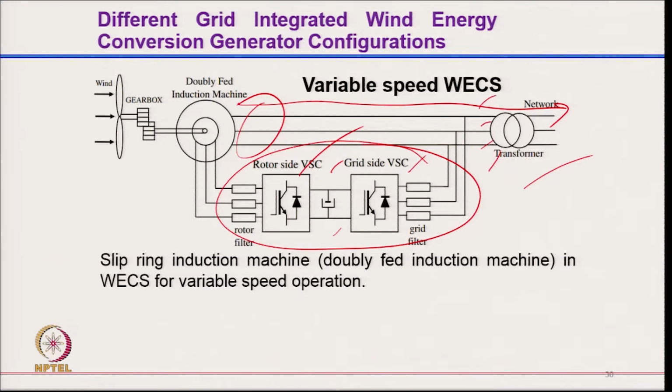Moreover, of course, you use the gearbox, because machines with 4 poles run at typically 1000 rpm to 2000 rpm, so that you can have MPPT. Around 75% of manufacturers are manufacturing this doubly fed induction generator, because the speed range from 1000 to 2000 rpm is enough for this wind energy conversion system. And here the processed power is hardly, typically, with 1000 to 2000 rpm and a synchronous speed of 1500, you only process around 30 to 35% power. The power converter rating is hardly 40%.